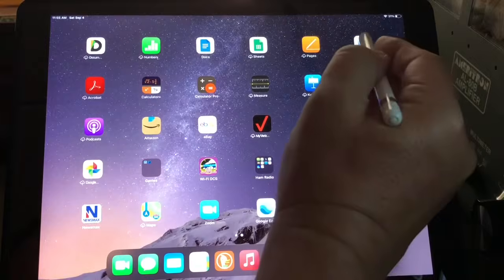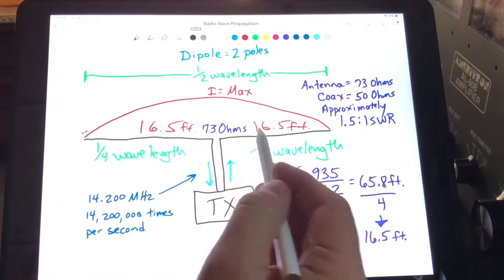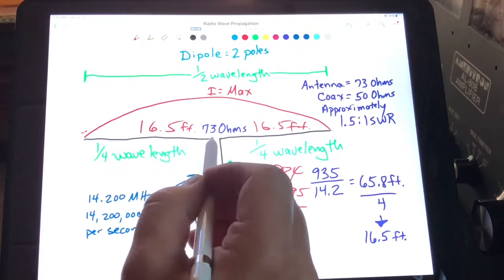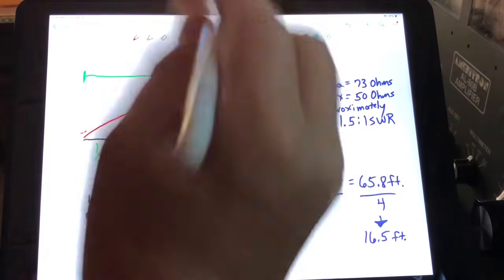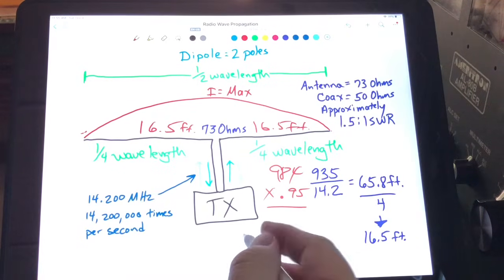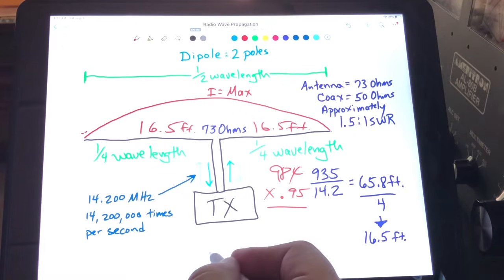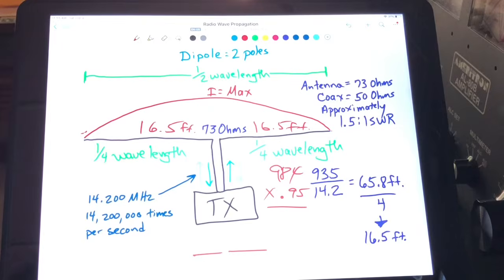The antenna is going to be able to produce for you somewhat of a figure 8 pattern off the broadside of these wires. So let's say we're looking down from an airplane or a helicopter at our antenna, and the wires run this way. All right? There's the center point, and our feed line's going straight down to our radio. What the signal's going to look like coming off of this from a helicopter looking down is more like a figure 8